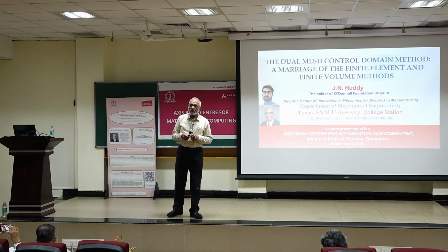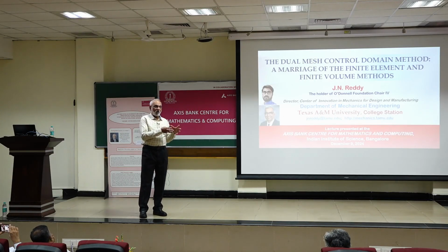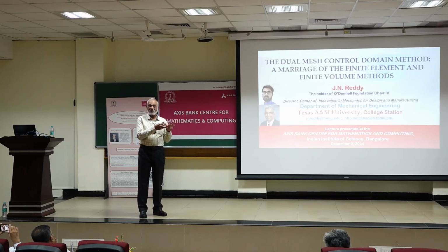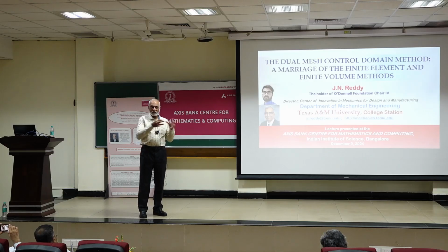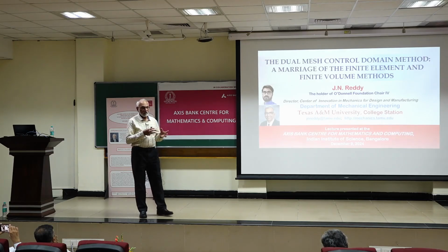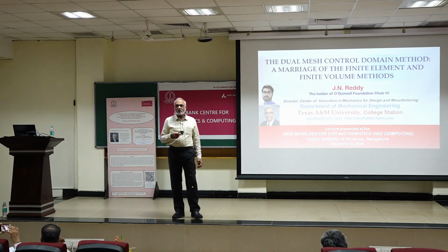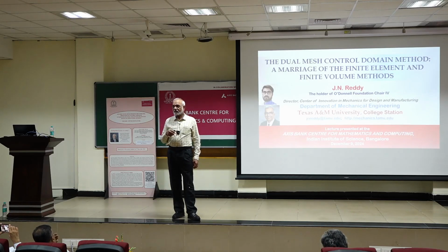But the finite volume method, those who work in that area, largely inherited all of the good and bad from finite differences, because the same ideas are borrowed into finite volume. The only difference between the two is that finite volume uses the balance equations in an integral form, what we call a global form of the physical laws, and then goes back and replaces the derivative using Taylor series expansions.